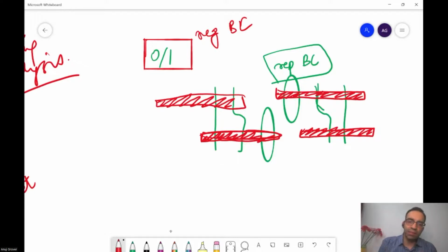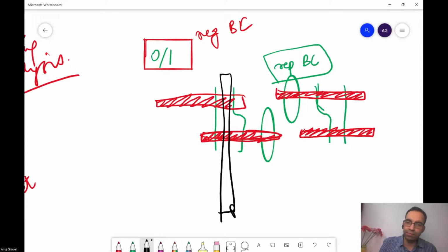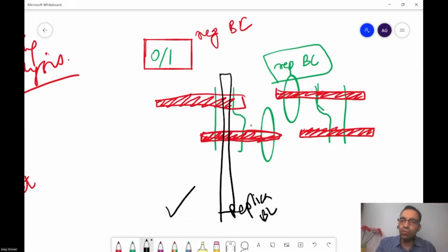But the thing is, there is a replica bit line, let us say here. This is your replica bit line. You want it to discharge in every cycle. If this has to discharge in every cycle, what should be stored on this particular node? Yes, sir. 0. If this gate is at 0, will this bit line discharge?